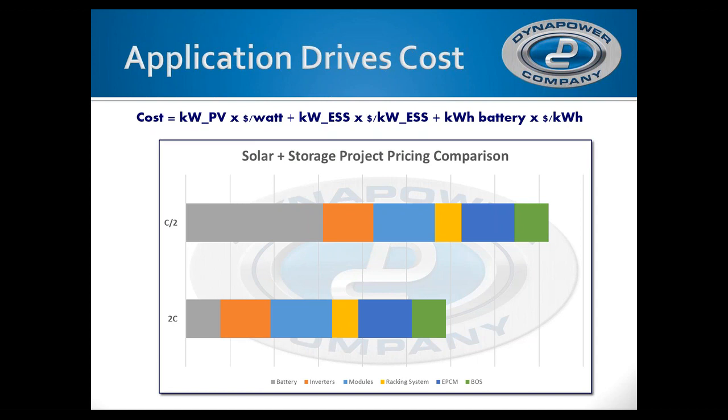So this represents, and typically a great battery for that application is a lead-acid battery. Flow batteries as well fit into that sort of category. They have lower C rates, higher energy, but you're also paying for that energy. And that's why that gray bar is a bit bigger as a percentage of the total project when we're looking at these lower C rate, higher energy batteries.